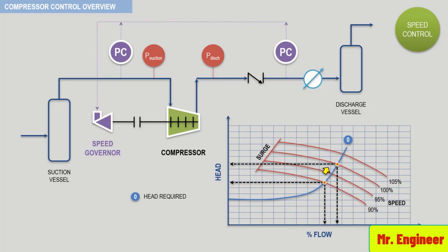It is true that the initial cost of a VFD can be 2 to 3 times the cost of a fixed speed motor with throttle valves, but the long-term power savings can easily be justified. Now, the change of flow rate, compressor head and horsepower as a function of speed are provided by the fan laws, as seen here.